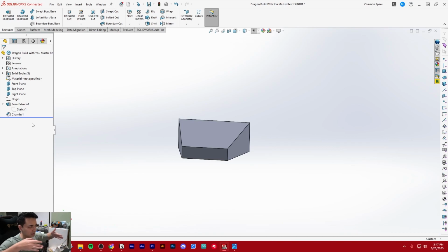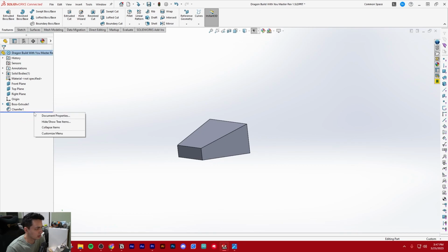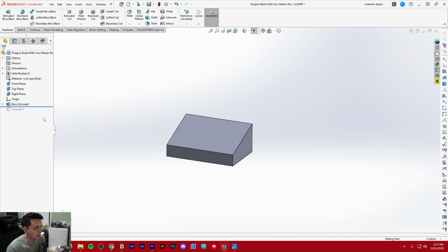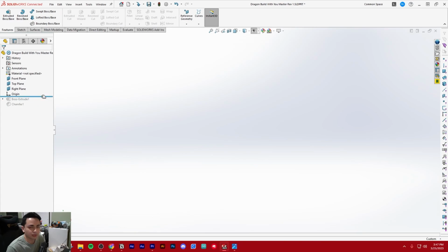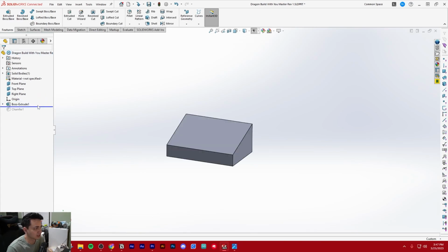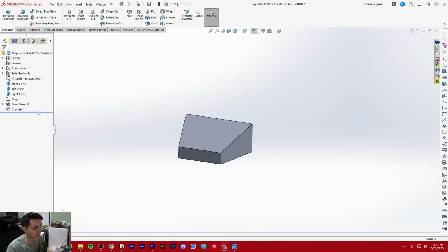It's getting smaller the more forward that it goes, right? Also, this little bar is really cool. Basically, you can roll back. It's called roll back. If you drag it above a feature, it'll pretend that feature temporarily doesn't exist. So you can trace back your steps in your history to see what's going on in your model. It's super useful. I use it all the time.